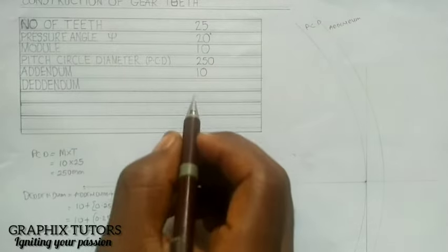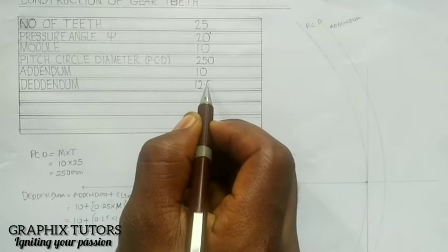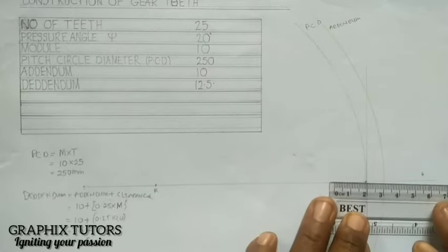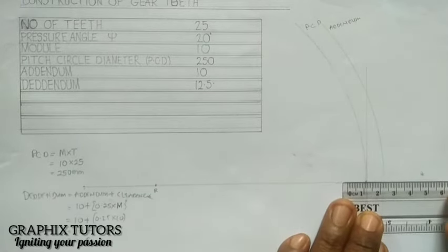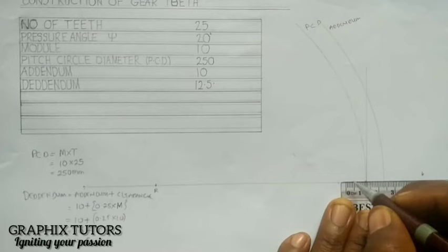12.5. So my addendum is 12.5. So what you do is this. From this point here, we measure 12.5 downward, or we know that from here to here is 125. So try 125 minus 12.5, and from 125 you get what you want. But the best way to do it is just measure 12.5 downward. So I'll take my meter rule and measure 12.5 downward here. From here this is 10, this is 12.5, somewhere around here. Are we good? So I'm going to just measure it here.